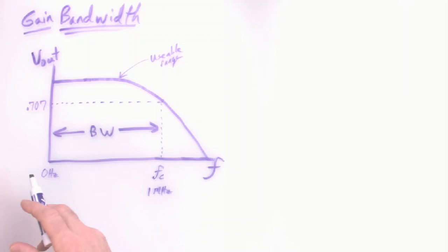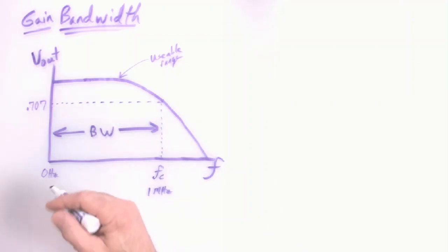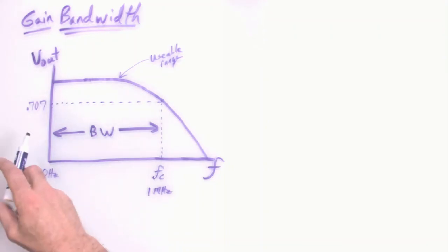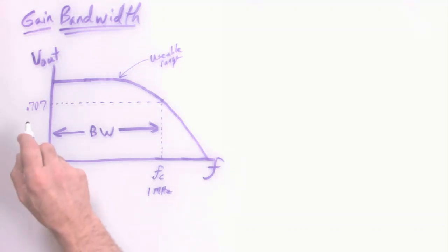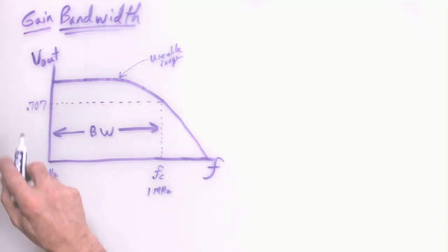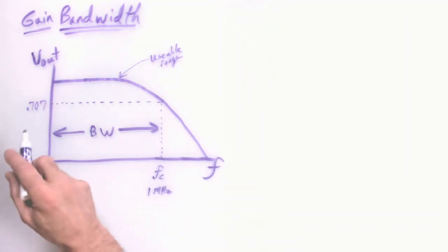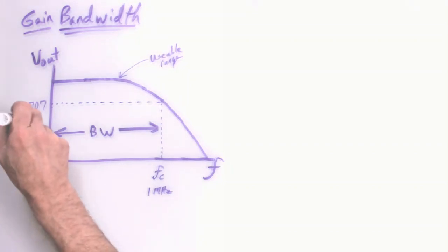Whether it's high pass or low pass, depending on your components, we'll look at the voltage division that occurs, and there's sort of a symmetry there to this 0.707. So there's lots of reasons. Let me look at the other definitions. 0.707. When your voltage drops to 70.7% of what it was, that is also going to be the half power point.